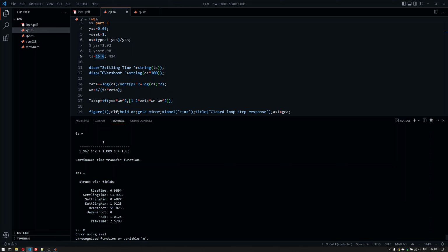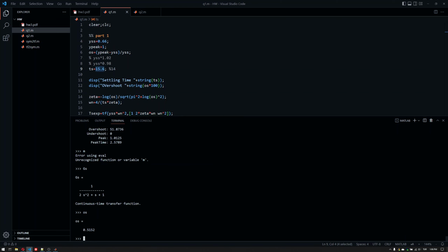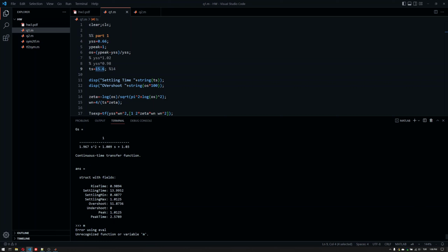We can approximate the overshoot quite well, by the way, which is important to note because we are looking for the peak value here, so it's not really that difficult to mess it up. But settling time is a whole different story because we can mess up stuff there. The settling time formula accuracy comes into play, and various differences end up being quite important here.